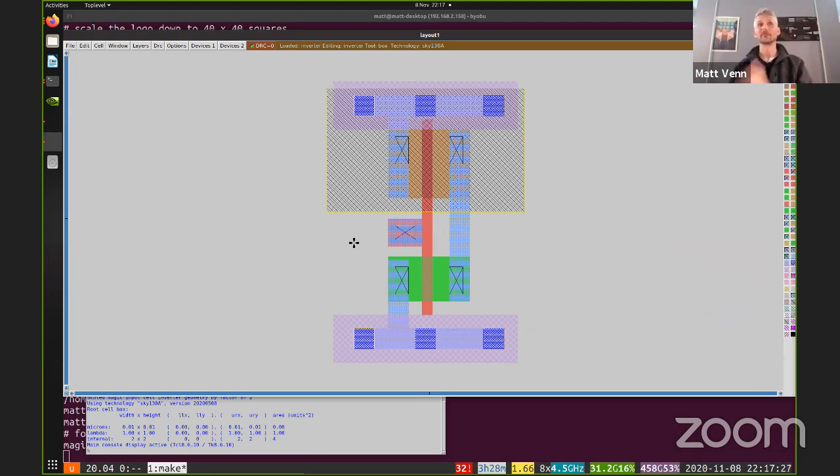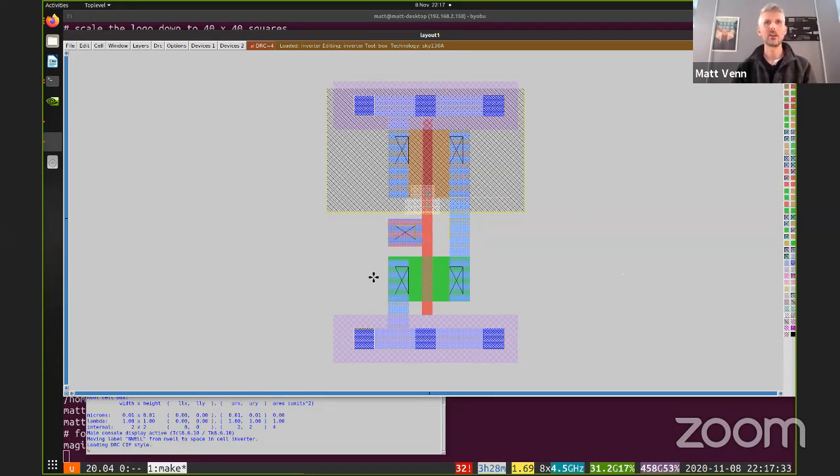So here's one I drew earlier. But I'll just show you now, if I wanted to make an N-channel MOSFET, what I need to do is draw where the N-type dopants are going to be implanted. And then I need to draw the gate. So that's made of polysilicon, middle click there.